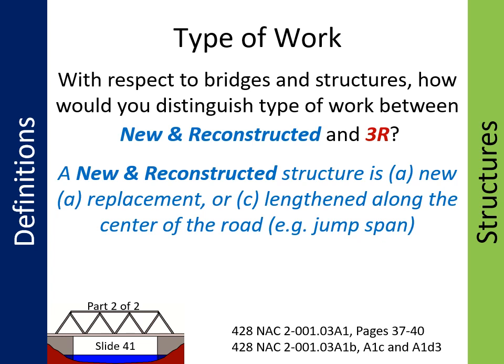Another phrase you may hear for lengthening a structure is adding a jump span. A jump span is an extension at the end of an existing structure, necessitated usually by a flood event or events, which severely scour an erodible embankment at the structure.